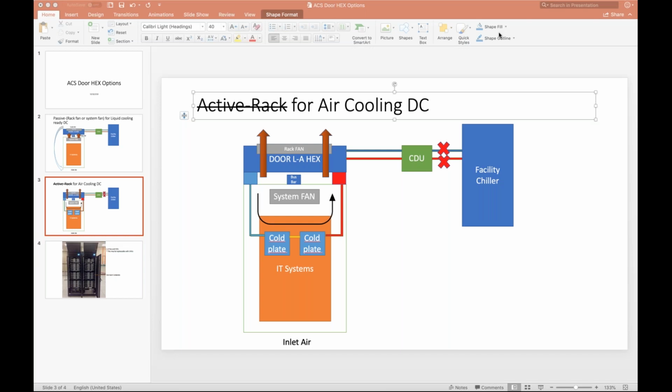I think the way Jacob has it in the drawing is that the heat exchanger by itself would not be directly coupled to the cold plate, right? You'd have to go through some sort of CDU. But the CDU is only responsible for driving the internal loop, right? So there would be no plate heat exchanger that is usually involved when you have facility water. I think this use case is being described for a case where facility water is not available. How can you use cold plates in such a case? You could have an internal closed loop in the chassis, but if there are too many chassis, then it's better to move the radiator to the rack. And I think that is what Jacob is describing.